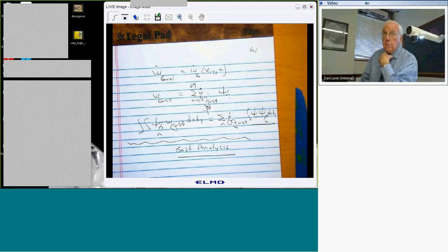In fact, I think more often it's a control surface, at least by the time you get to flight test. There are enough uncertainties about your control surface, particularly in terms of aerodynamic representation, that even an experienced aeroelastic team might predict that everything's going to go just fine, and then you go out and flight test or wind tunnel test, and you find that one of the tail surfaces has a little bit of an issue.